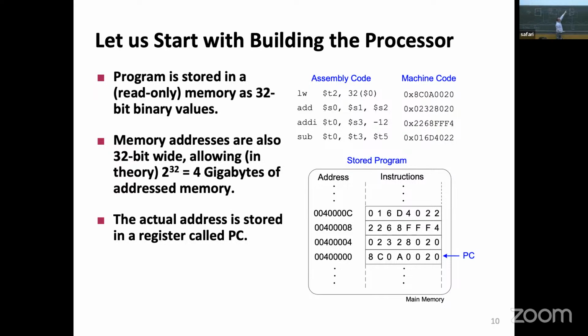Okay, what do I add to? Second register? No. I'm not going to add to this register, because the second register is not something I read from. The second register is actually where I will be writing the value to. The result will go, instead of this one, somewhere else. Now that's annoying. So it means that I have 2 options. And 2 options usually means that I have a nice circuit structure that we call a multiplexer.